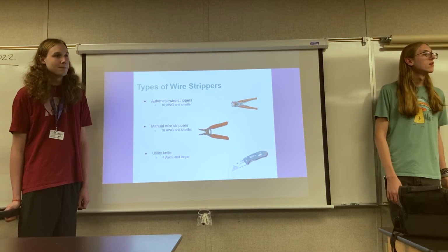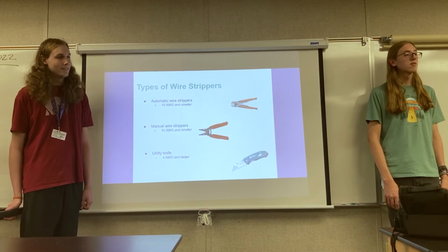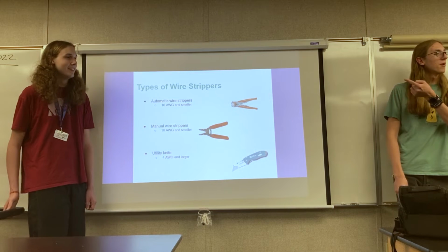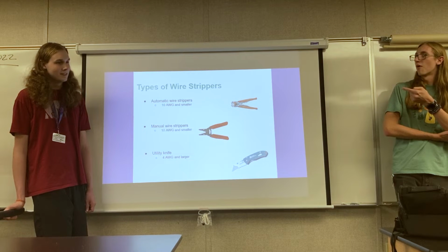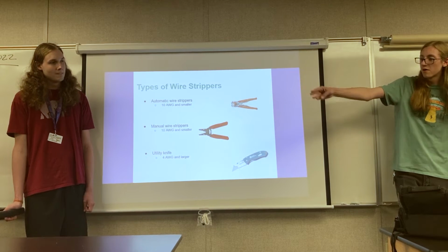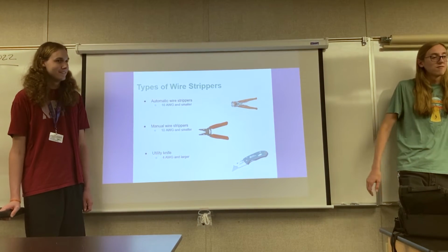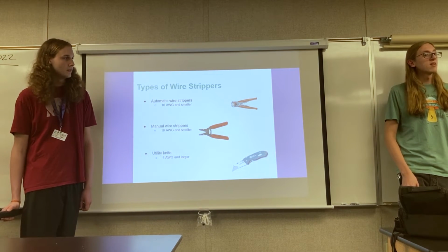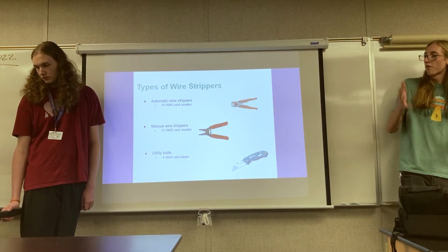Anytime you do any type of soldering, or anytime there's a connection, you have to cover the wire. You can't have any exposed wire at all, otherwise it could start a fire. I believe we had a problem last year where the robot was grounded to something, and we almost failed an inspection because it was passing current through the body of the robot, which is metal. A giant taser. Always make sure all your wire is covered, even with electrical tape, because if it's not covered properly, it could arc to another nearby wire and short out components of the robot.